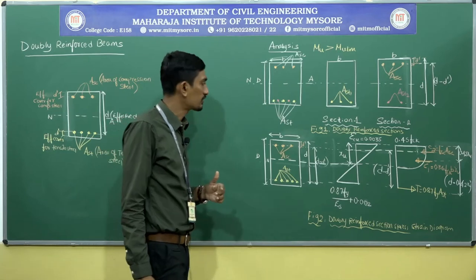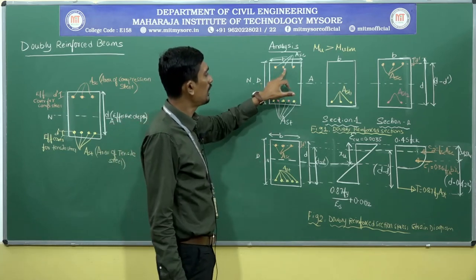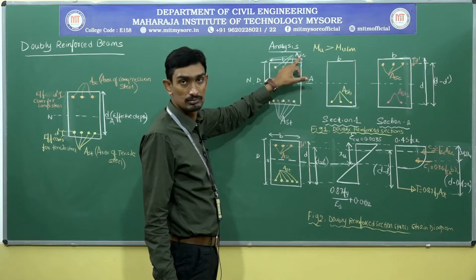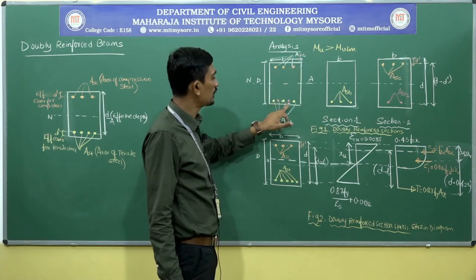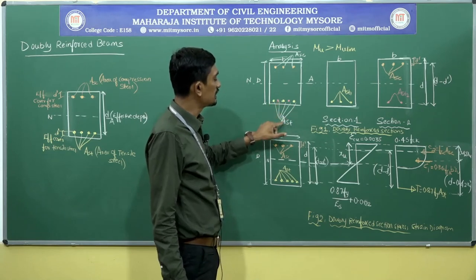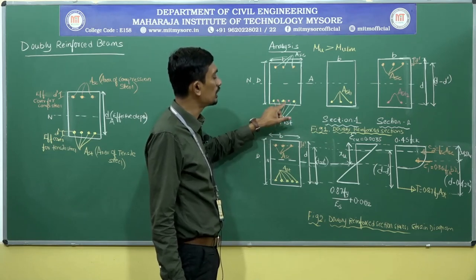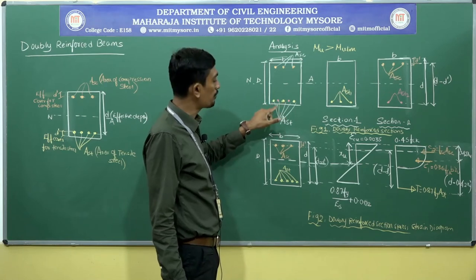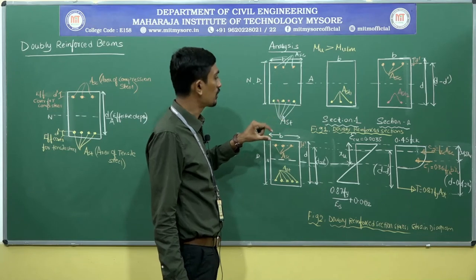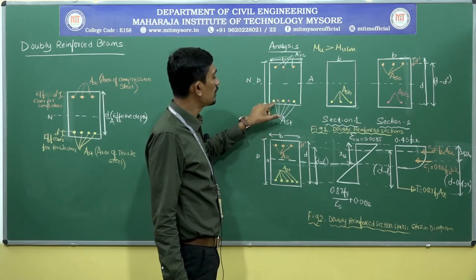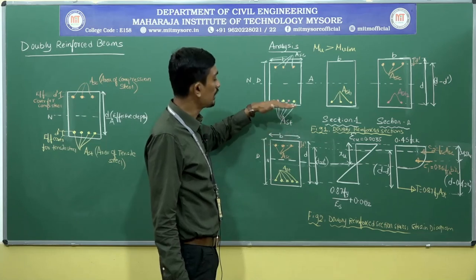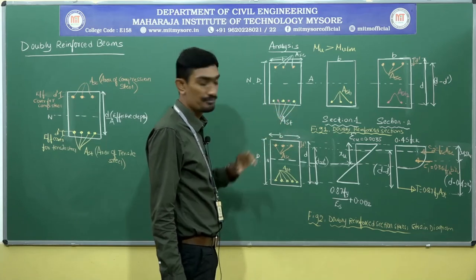Next, these are the area of compression steel, denoted by Asc. And the Ast has been defined with two colors, yellow and pink. I will make you understand what exactly that is. So, 3 or 5 bars have been accommodated in the tension zone, and that is Ast.